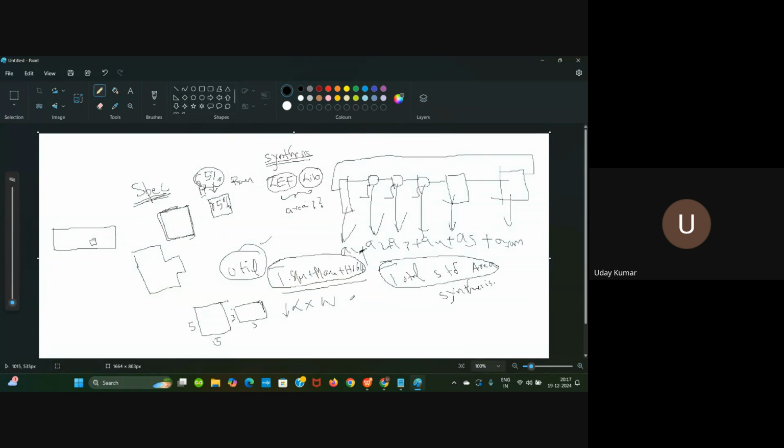You can't reduce it manually, but you need to control the tool such that it will not add higher drive strength cells while optimizing the design for timing or power. Higher drive strength cells take more area compared to lower drive strength cells. These are the two different area optimizations you do.